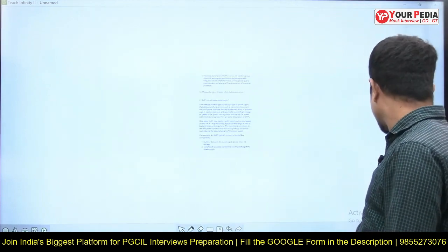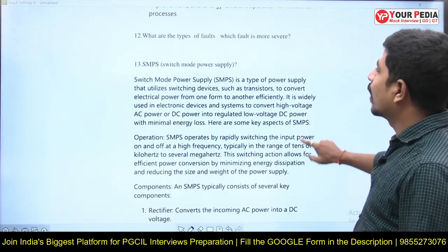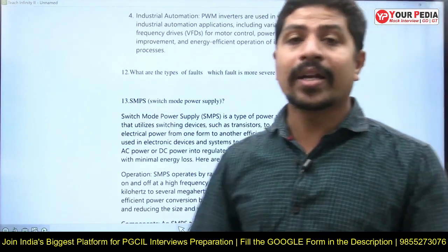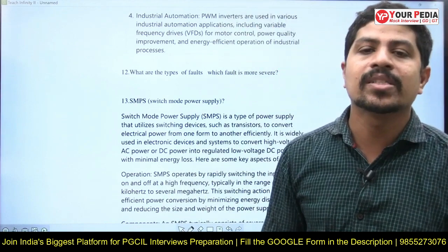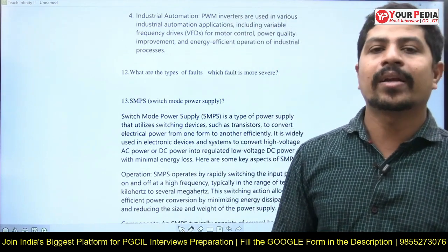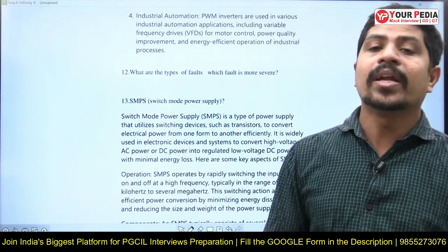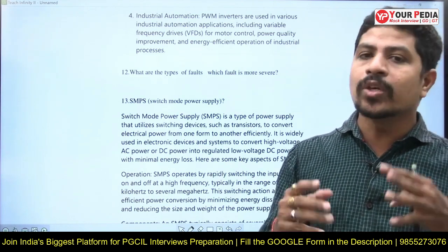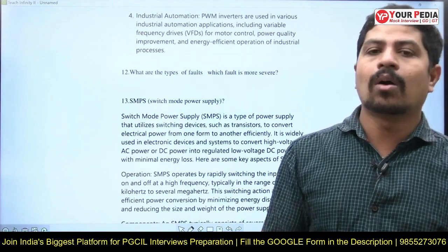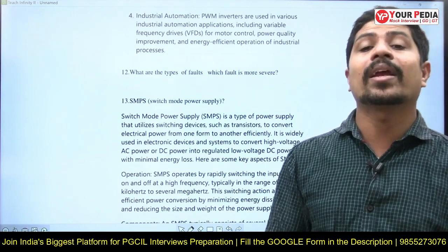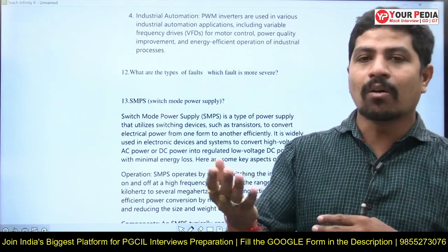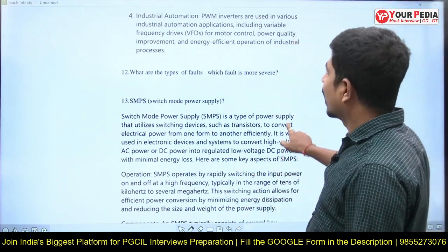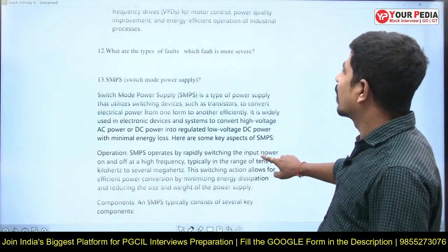Motor drives. What is a drive? An electrical machine with a power electronic converter connected to work according to our requirement is a drive. An electric motor is there. Suppose you take an induction motor connected with power electronic equipment, that equipment is intended to give a required amount of voltage or frequency to it, so that I can get my required mechanical output, speed or torque, whatever it is. So that is a drive. Another application is industrial automation, which we all know.